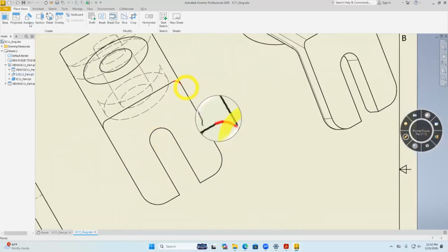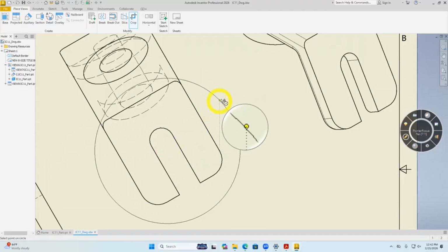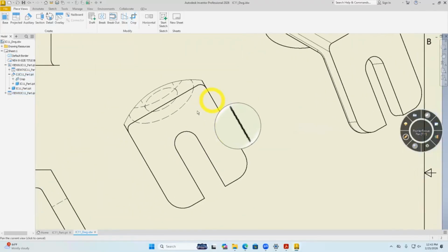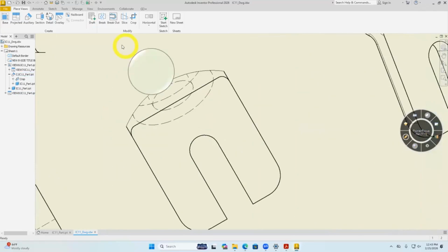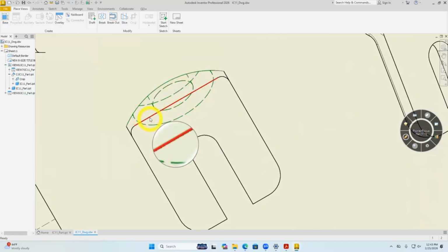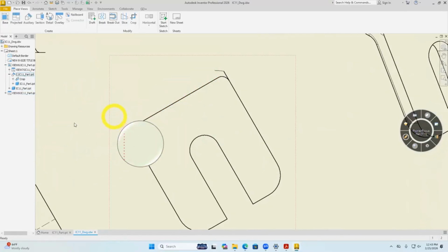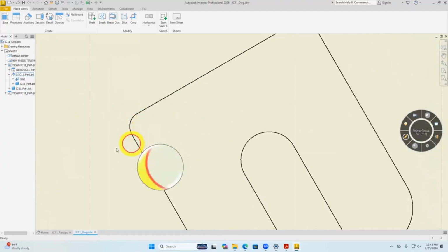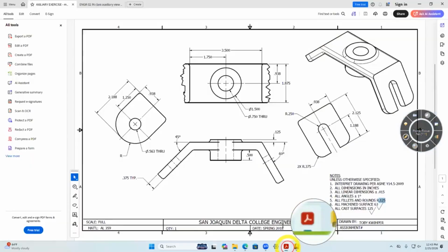In this case, I want to crop it again. So I'm going to go to the crop, select the view, and I actually want to do a circular crop. I'm going to go somewhere by Y and somewhere by Y. I don't want those lines in the middle, so I'm going to do a window. If you don't want something, select it, right click and hide it. Do the same concept over here. Right click and hide it. There's no visibility. Let's go back over here.